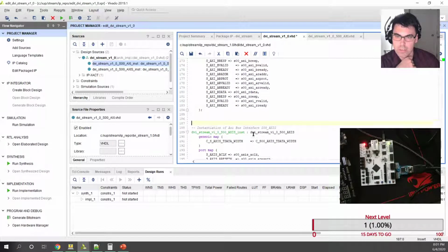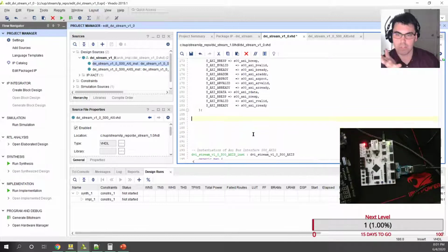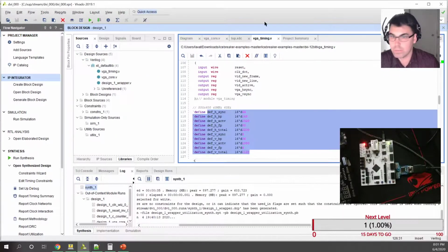And this HDL is going to take in the pixel clock, the configuration registers, the data, and it's going to output the colors when it needs to. I mean, basically when it's not blanking, when the active signal is high. I assume that's what's happening, right? I mean, let's go look at the other project real quick. Not that one, this one, right?